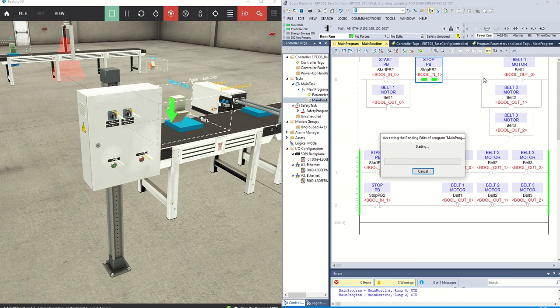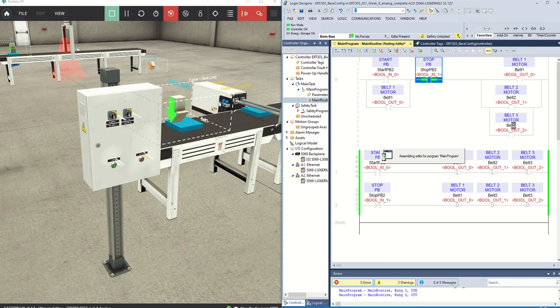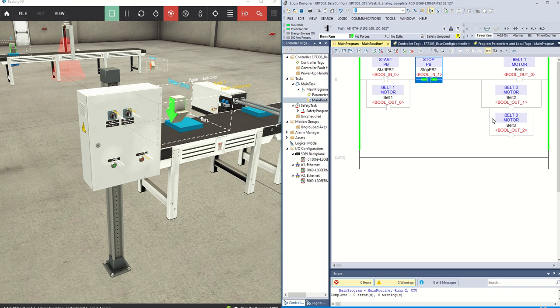And there is a difference in the way this scans in the PLC versus the way I'm going to show you in a second. So cascading branches is not a good thing, for a couple reasons like that. It looks very similar to what I'm about to show you, and you'll see this does work fine. But this is not the best way to do this.